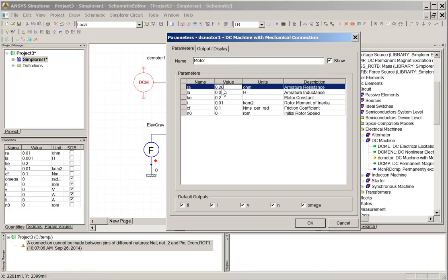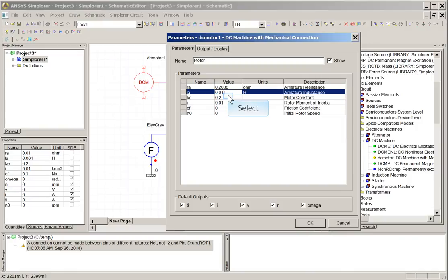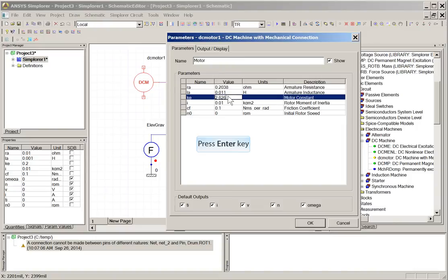And we'll cover this in more detail later in the course when we talk about DC machines. My inductance is 0.011 henries, or 11 millihenries. The motor constant in Gross's textbook is called Ka phi, and its value is 2.626. That's what describes a conversion of current to torque.